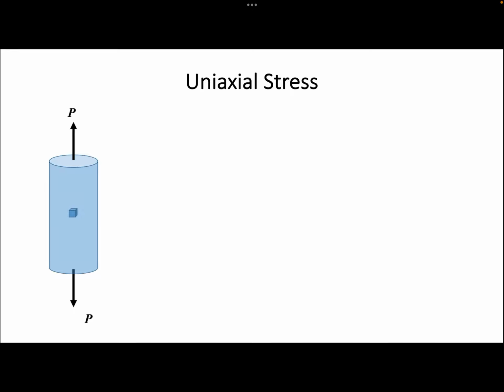Now, in order to help you better visualize the stress in the above example, let us consider a small volume element at the cut location with the top and bottom surface oriented perpendicular to the longitudinal axis of the bar. Based on the previous slide, we know that there exists only normal stress at the top and bottom surface of the element. Then, if we plot the free body diagram for this element